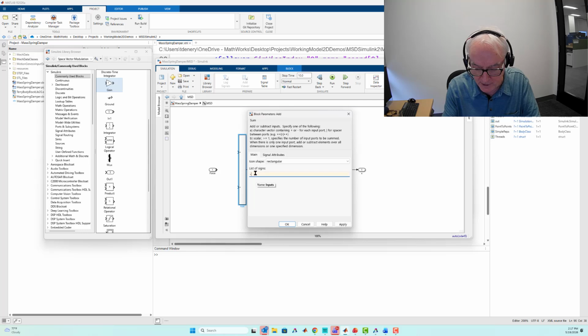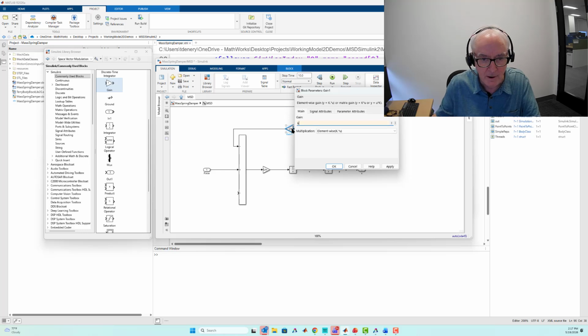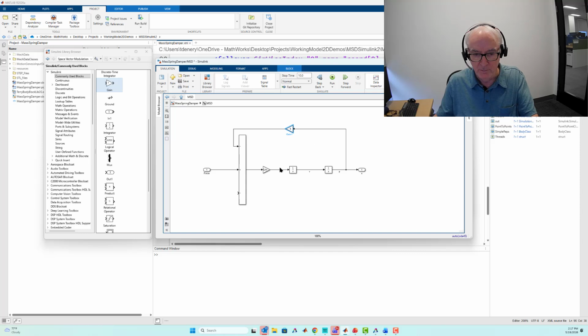And so I'm going to set up with inports being 2 minus, so it's going to be minus plus minus. I'm going to put the minuses on the outside and the plus on the inside to receive our applied force, right? And that spring force, of course, is based on position, and it needs a proportionality constant, which we happen to call K. Right? There's K right there. That's basically multiplying it by 100, and then we'll do the same thing to get the damping.